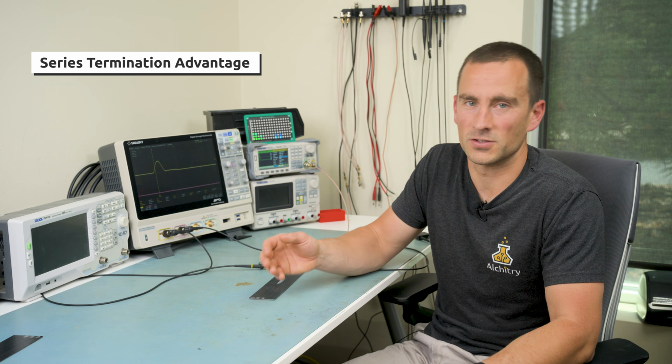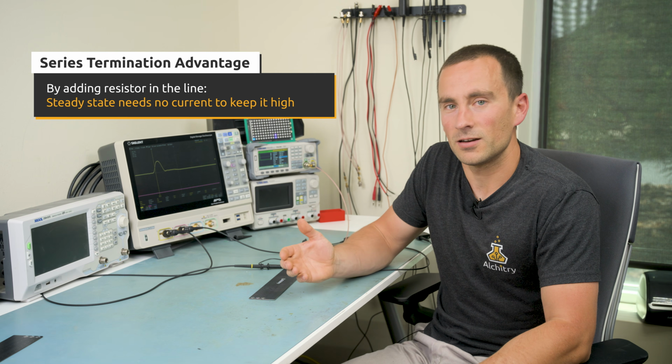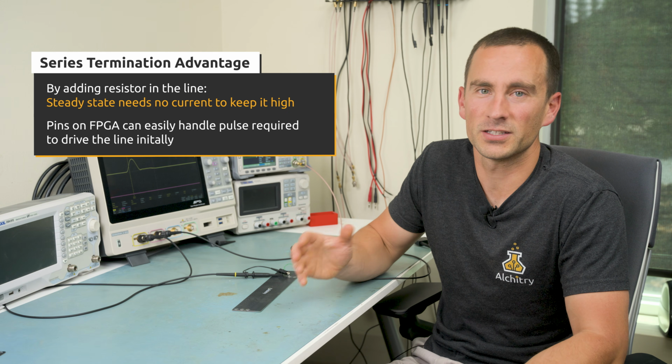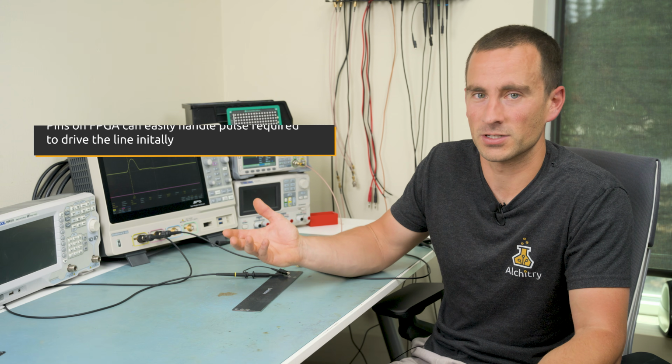This is the real advantage of series termination. By adding the resistor in line, when the line is in steady state, we don't need to provide any current to keep it high. The pins on an FPGA can easily handle the short pulse required to drive the line initially. After all, they have to do that every time they switch a signal anyways.